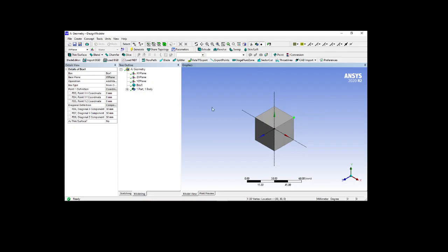Next, if you want to select multiple points, then press the control and left click the multiple points. If you want to avoid that, just right click into a space. Next, here also same, for line selection you may press this icon, and if you want to select this edge, left click it. If you want to select multiple edges, you can press the control and left click. This is how you are able to select multiple edges by pressing the control.